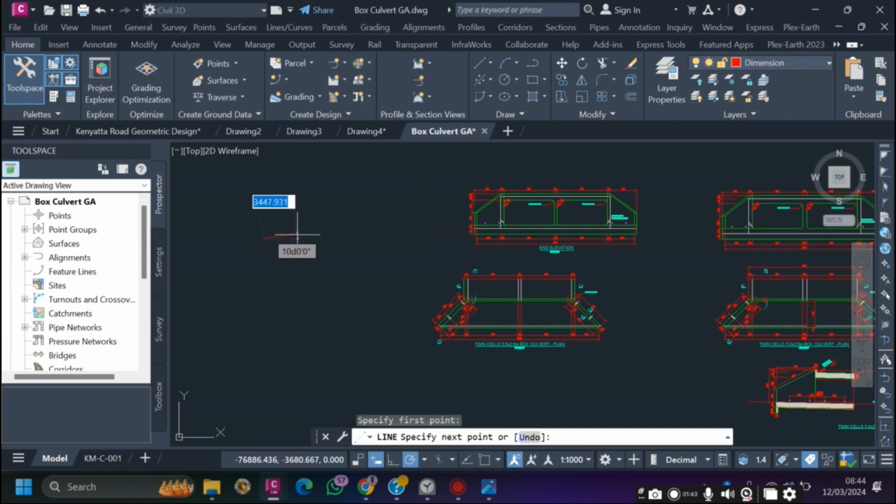You just click anywhere on the screen, and then it will ask you to specify the next origin. In the next origin, you can specify the angle, the direction, wherever you choose, you move your cursor, and also the length of that line. Better yet, you can use L as a shortcut, and then you just press enter, L, press enter, and you can still create a line.